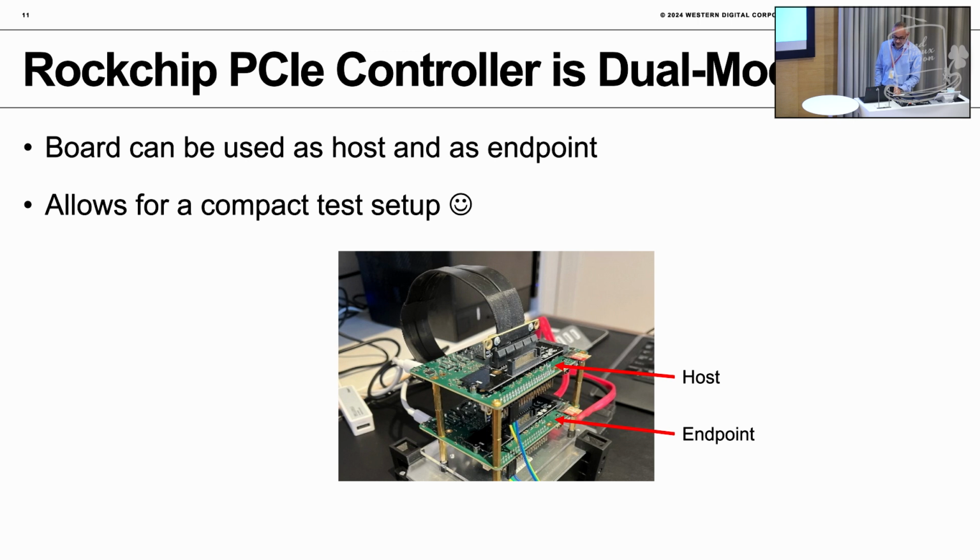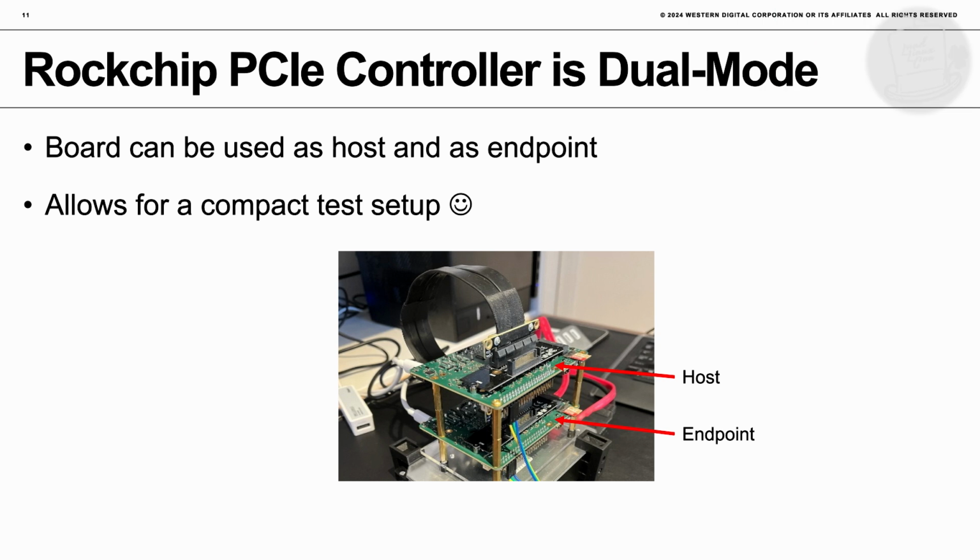Bonus is that like most of these controllers that can do endpoint, of course, it works also as a root complex. So you can use 2 boards, one as host and one as an endpoint, and you end up with a very compact test system, which is extremely convenient to just put on your desk to do your testing. Of course, you can use as a host any normal PC, but why risk it, right? You'll see that there are gotchas to be aware of when you plug PCI cables like this from an endpoint board.